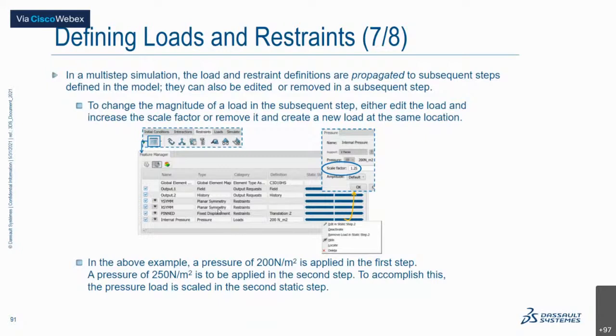So you can define an initial pressure, and then for a given amount of time, that initial pressure will be acting onto your tank. Eventually you can define one more point where the pressure changes to a different value, and then you can define the pressure values there too. So it will be a multi-step simulation that you could use. This is helpful for situations wherein two different types of forces or pressures are to be applied to the component.